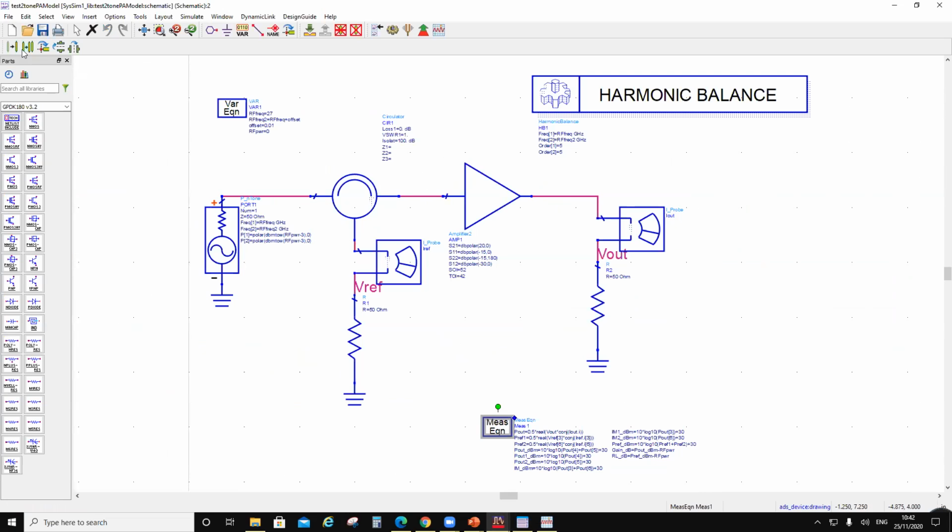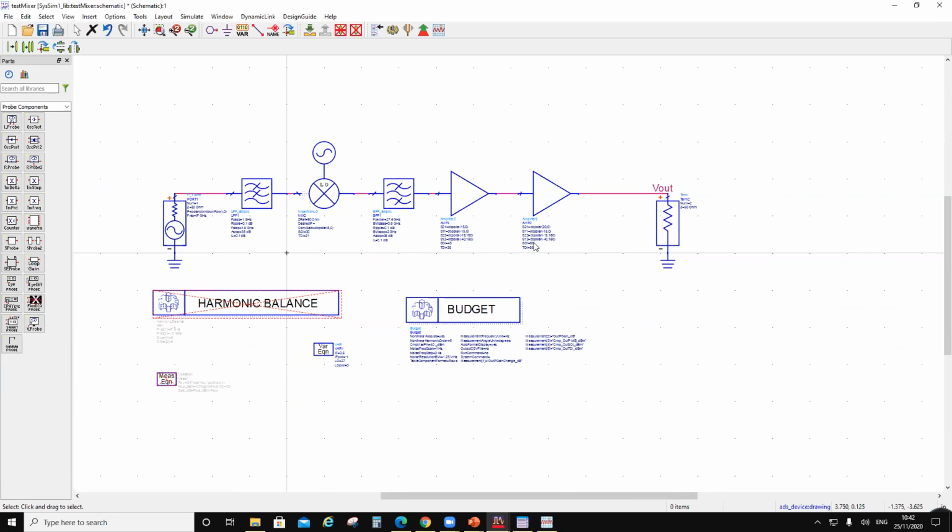Now, the same thing you can carry out on a receiver chain. So by this time, what is the takeaway from this exercise? The takeaway is the following. When you put together this chain, you should know what the power delivered should be. So you should start from here. Not from here. We started from here. That's a wrong thing to do. On a receiver, you start from here. But from the point of view of a chain, you should start from here.